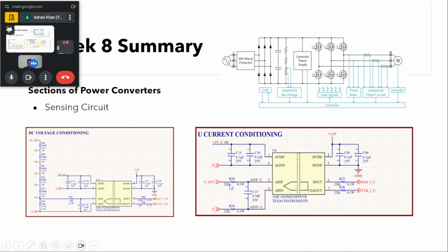After that, we'll be having some RC circuitry which acts like a filter, and then that is given to this sensing circuitry, which, like I told you, is an isolated amplifier. Then it will provide the output which we usually give either to the conditioning circuitry or to the microcontroller.